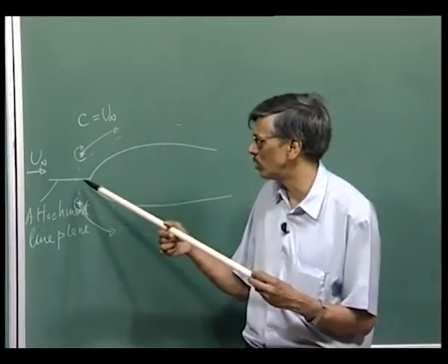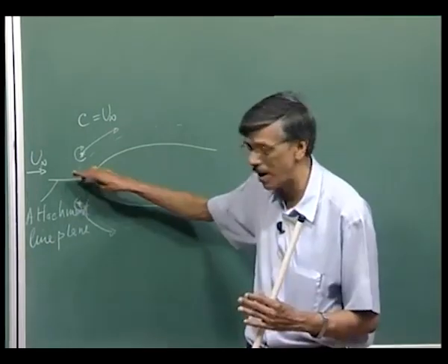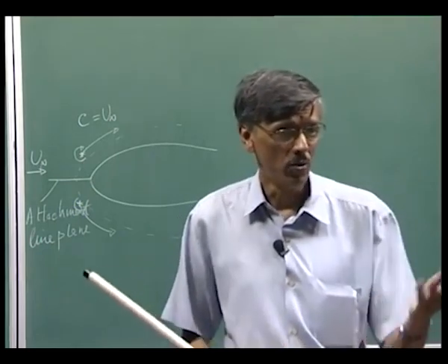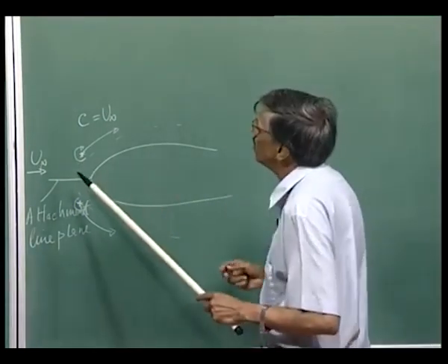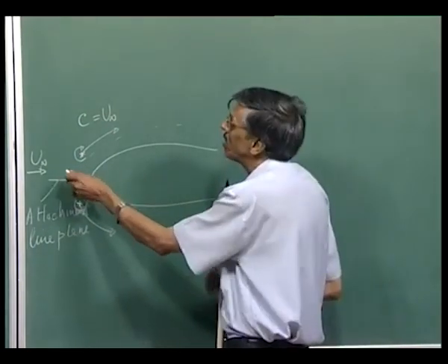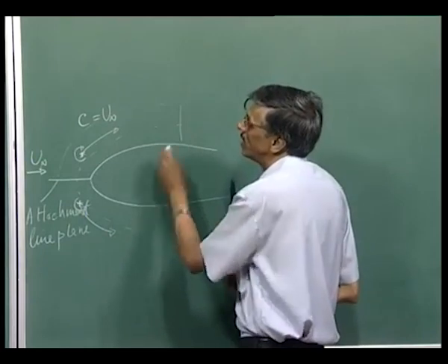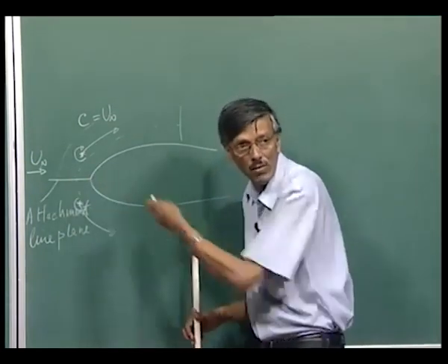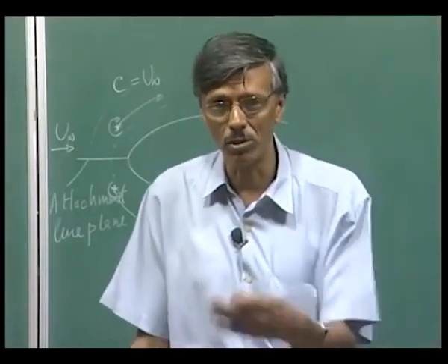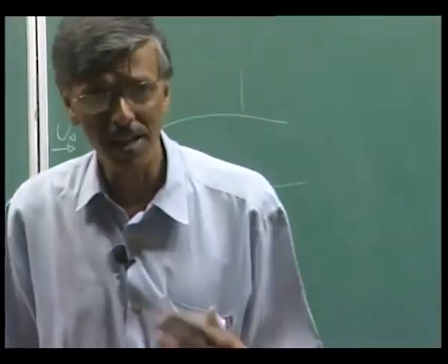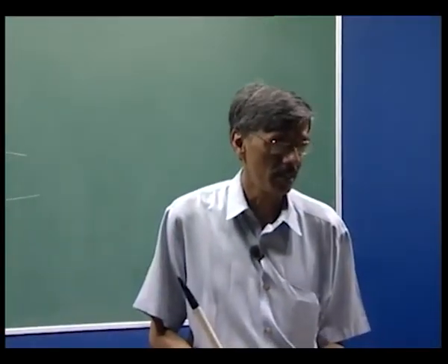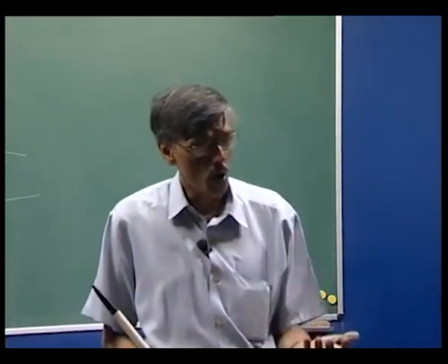We were discussing a periodic vortex moving in this plane itself, and I kind of suggested that one could perhaps investigate what happens to a flow domain if we think of it as some kind of a natural barrier, and then we can construct a flow domain like this, and due to this inflow unsteadiness, what will happen for the three dimensional flow field. That would give us a fairly decent idea of what happens as a consequence of attachment line instability for the flow over the wing.